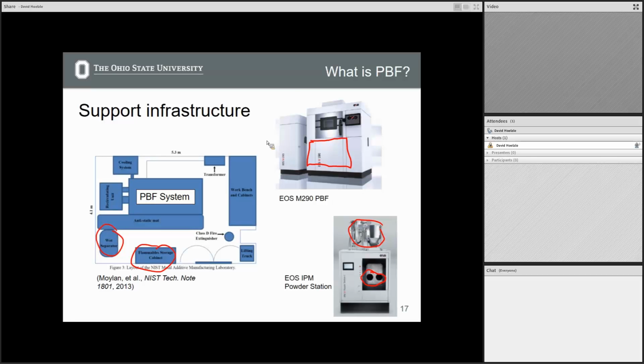The reason they have to do that is because 3D Systems is trying to make their name by having smaller particle sizes than everyone else. So you get finer, better surface characteristics than everyone else. And with that comes an increased chance of causing explosions, so they have even more safety systems involved. They also do other things. Instead of just using a recoater blade, they actually compact the powder layer at every layer to get higher densities and lower porosity. They're trying to create the best quality parts possible, and that of course boosts expense.